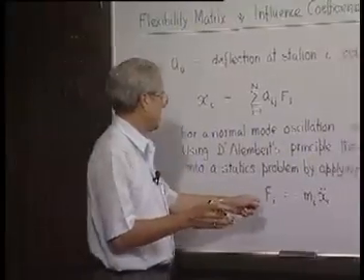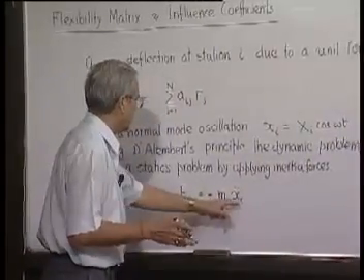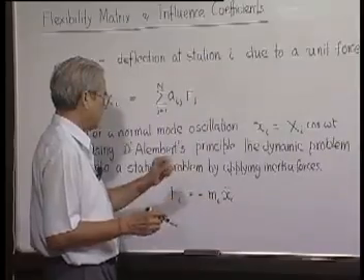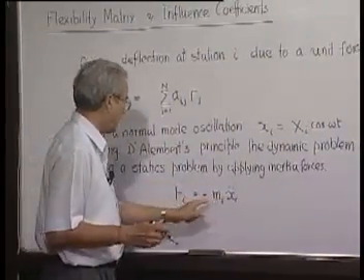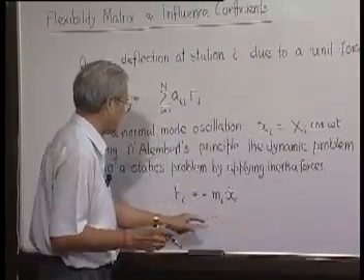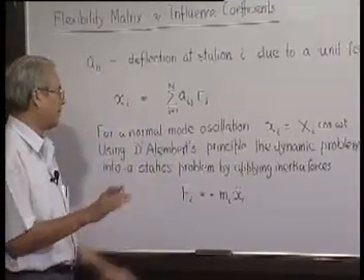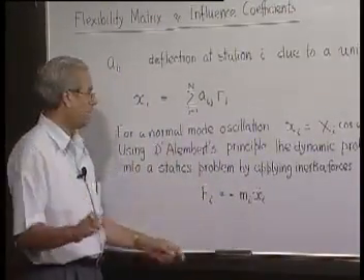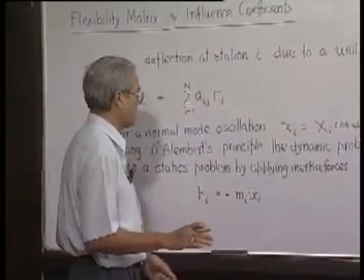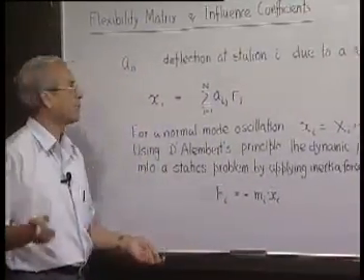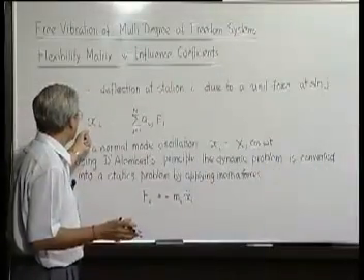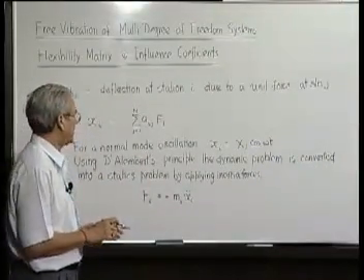That means at any instant we use the acceleration of that station multiplied by the mass of the station, and negative of that, as the inertia force. We assume that it is being applied at the ith station, and the combined effect of all such inertia forces, in the absence of any other force because it is a free vibration, gives the displacement. So, thus